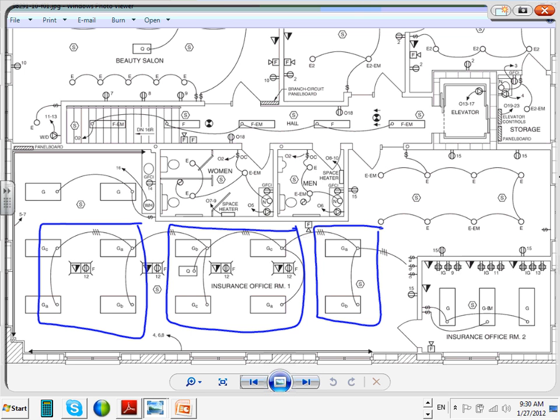The other thing I want you to look at, Nick, my friend, is that they are using floor receptacles. Can you guys see the floor receptacle? I know we're done with power. That's exactly, Chris, what they use for these underfloor raceways. Inside that floor box, they have a receptacle and phone and data, 2 sections: 1 section for the low voltage, 1 for the high voltage. Any question, guys, about this? That's the insurance office. They put a lot of isolated ground in a lot of stuff here because they want to isolate ground.